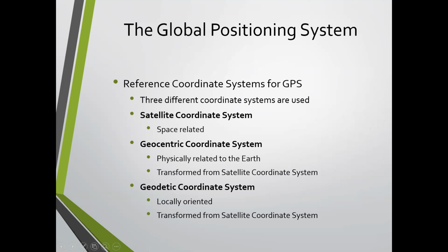And you would have another transformation theoretically if you were working in state plane. It would be translated down into, or transformed into, your state plane. So luckily we don't have to do any of this. All of this is done in the software end of your receiver. So when it spits out a GPS coordinate, or a state plane coordinate, I should say, you've got to realize what it's measured in is converted or transformed for you.